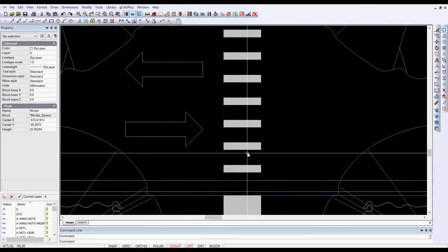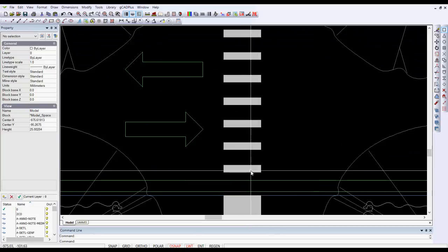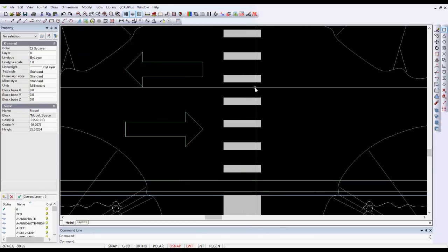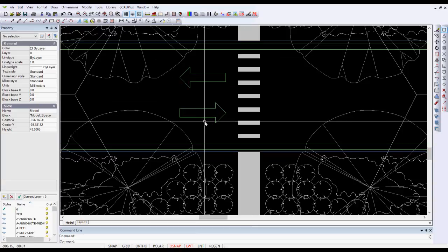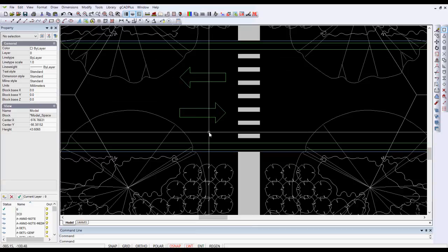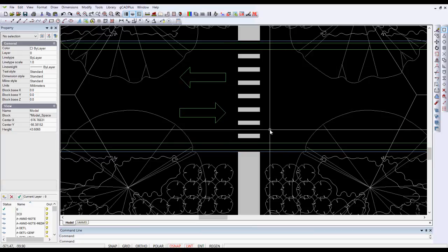And now we've made our drawing more efficient because we're using just a block for that, and we've removed that bluish tinge to it, which might or might not interfere with our plotting. So I hope that helps in manipulating the selection set, learning how to change a group of lines that make up a rectangle, turn those into a single polyline, filling it and adjusting the colour of a filled polyline. So we've overcome the need to do any hatching.